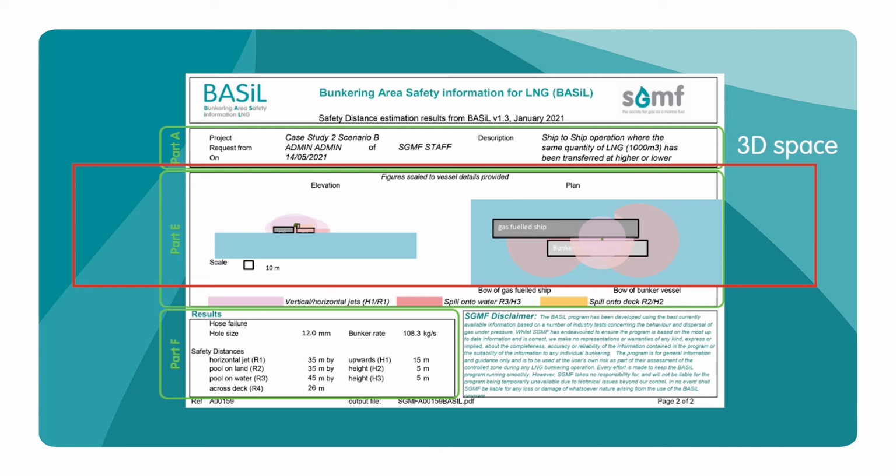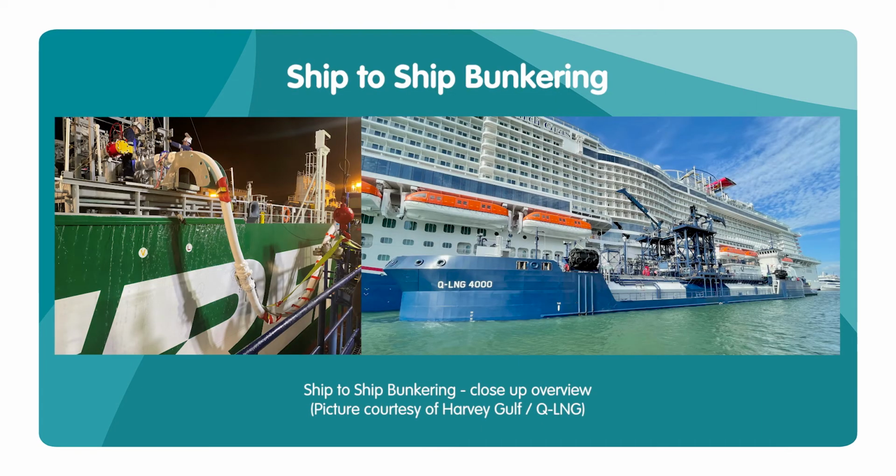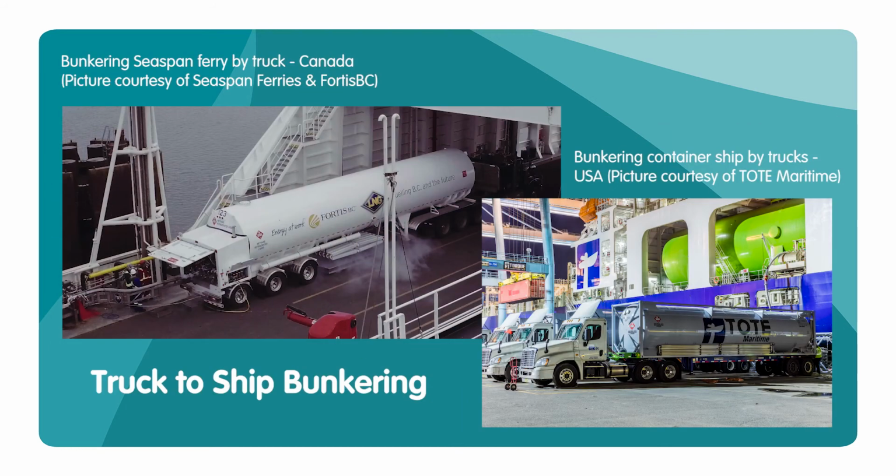The size of the safety zone is determined by the worst consequences of a defined leak, and the opinions and calculations are based on international hazard data for LNG and operational norms. SGMF has reviewed all possible bunkering leak scenarios to identify the maximum distance of impact sufficient to potentially kill an individual, based on an assessment by technical experts of likely leak scenarios.